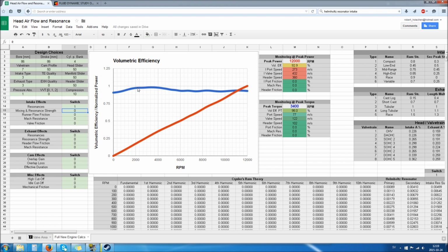And that pitch has only one real frequency in it. And then you have a second bulge here, which comes from the fact that your engine is not just a bottle, but a bottle which is connected to a bottle. What I mean by this is that you have your cylinder, which is the bottle, then you have your runner, which is the bottleneck, and that bottleneck is connected to your plenum chamber, and that plenum chamber is then connected to the outside world via a snorkel, which is another neck.